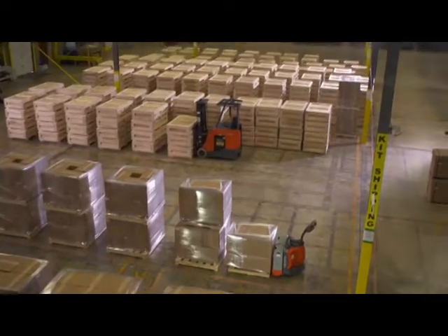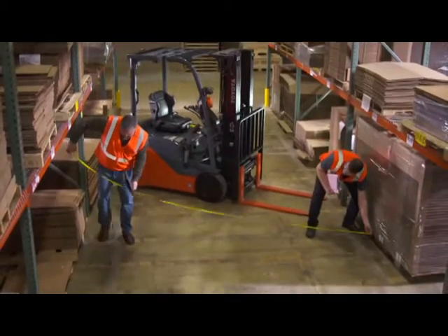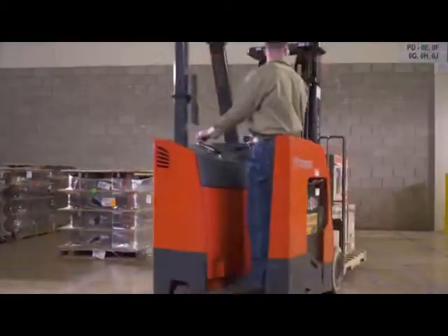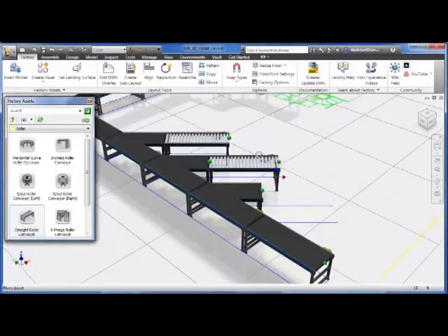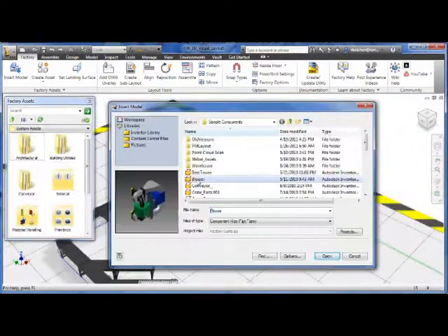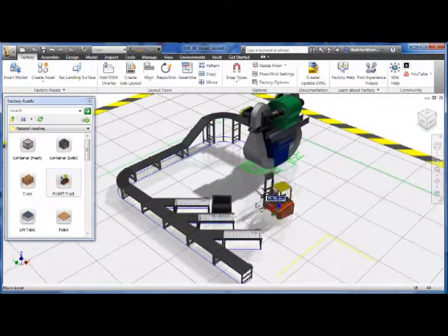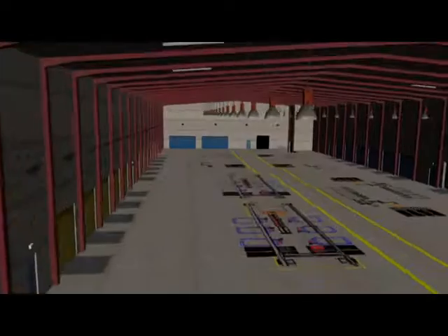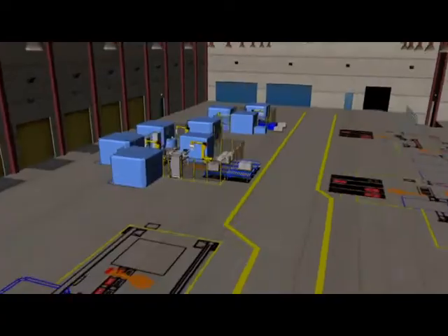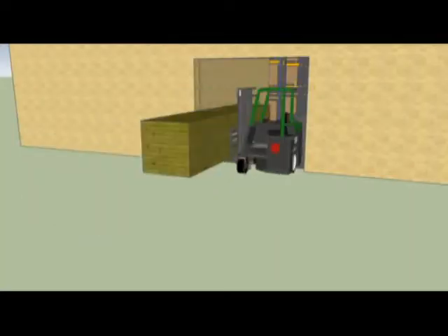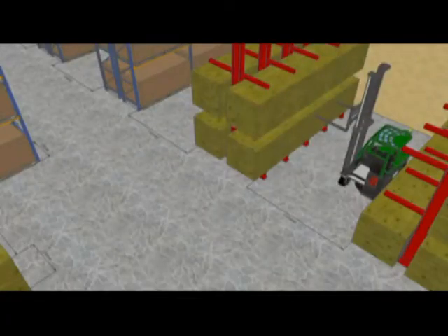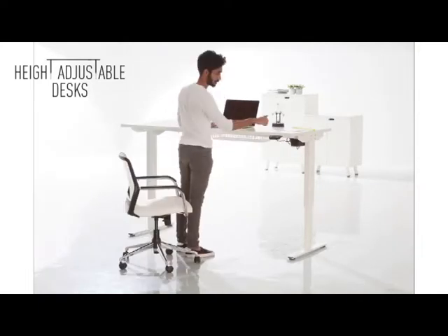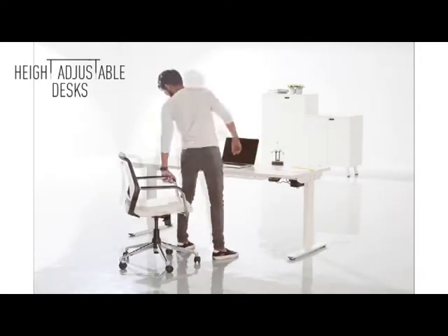Now you have enough information to get to step 10, the layout. Determine activity relationships. How close do departments need to be to each other to minimize people and material movement? You can use simulation software like Autodesk Factory to make the job easier. Layout each workstation. These layouts will lead to department layouts and then to a facility-wide layout. Identify needs for personnel and plant services and provide the space needed. Finally, identify offices needed and layout as necessary.